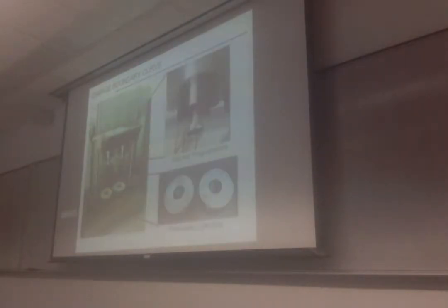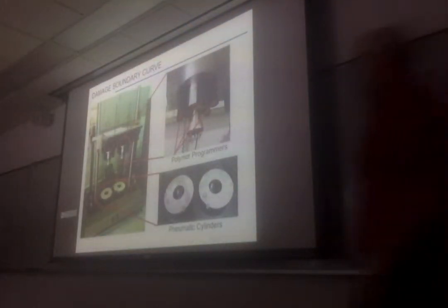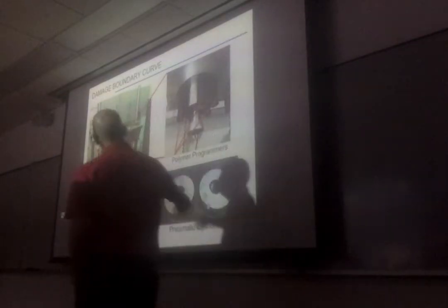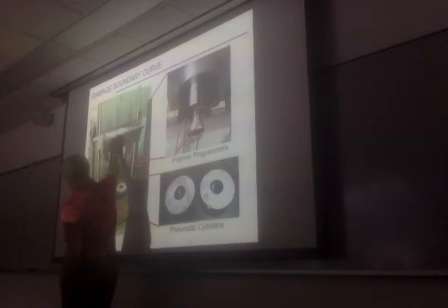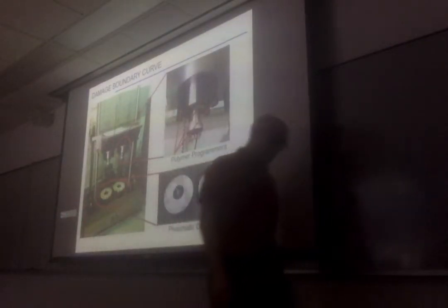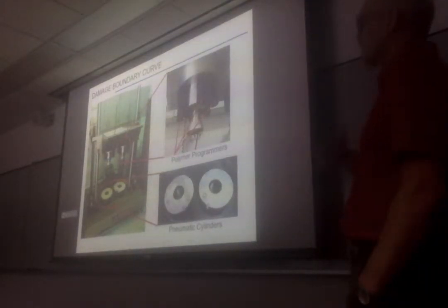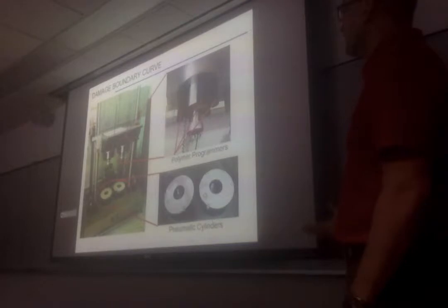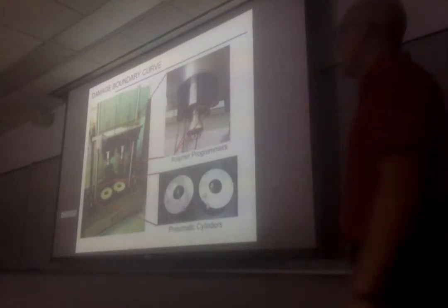So what are we talking about and what does this thing look like? This is a shock machine, and here we identify different components. At the top, that big chunk of metal is the table. You have a bunch of locations where you can bolt down the product on the table, because you don't want the product to fall off after the impact.